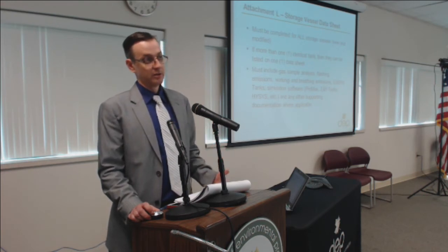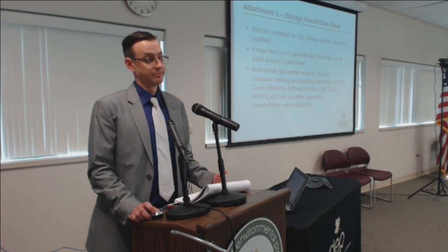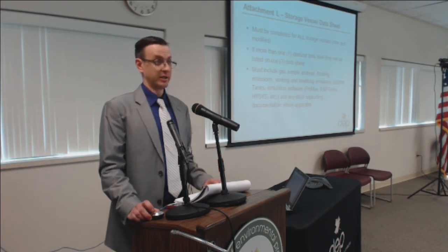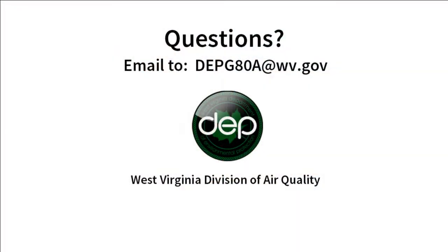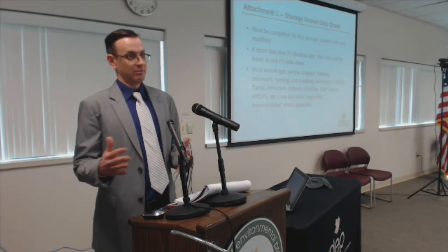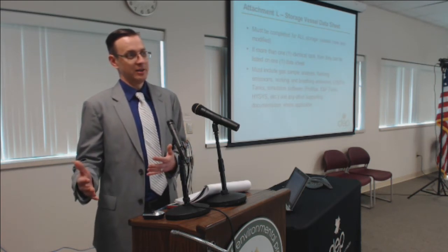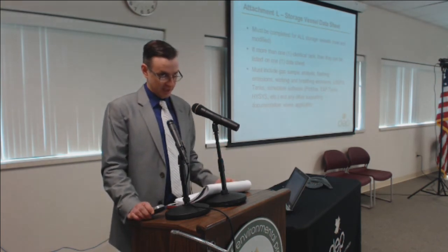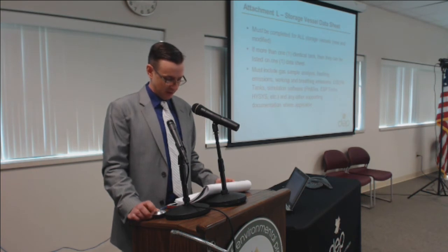You also need to include not just the output of whatever calculation methodology you use, but also any of the input values. I'm not saying this happens, but we need to know that what you put in equals what you put out. If we don't have anything to verify it with, it's just random. So we need the inputs and the outputs and the gas sample analysis so that it all matches up.